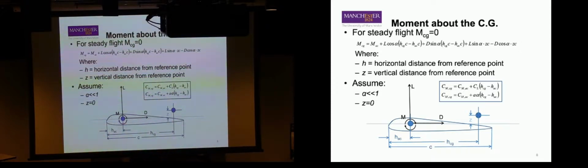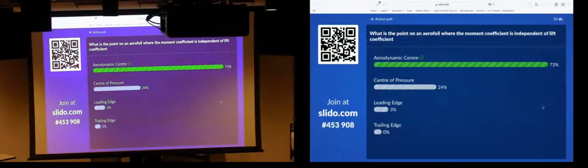A standard, conventionally cambered airfoil generating 0 lift. It's 0 lift angle of attack, has a nose-down pitching moment. The center of pressure is now infinitely far aft of the wing. If it's generating a nose-up pitching moment, it has to be infinitely far forward. So it doesn't even have to be on the airfoil. That's why we don't like it. We don't use it in day-to-day parlance. Would be nice. It's a nice thing. It's always nice where we just deal with pure forces, but that's not always possible. Okay?